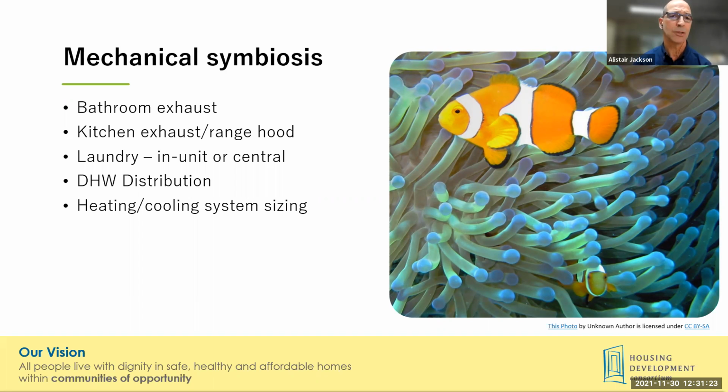And then, of course, because you're providing energy recovery, that's going to impact the heating and cooling sizing, and there may be some savings opportunities there. As I mentioned, there may at least be an opportunity to provide some cooling into the system if you're using a centralized system. And that's a consideration that should be weighed against other approaches to delivering cooling in a building.